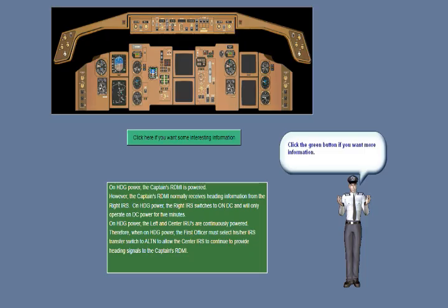External power must be manually selected. Pushing the switch to on closes the external power contactor and also trips off the APU or the engine-driven generators. After the external power is online, starting the APU will not cause the APU generator to automatically replace external power supply to the aircraft.